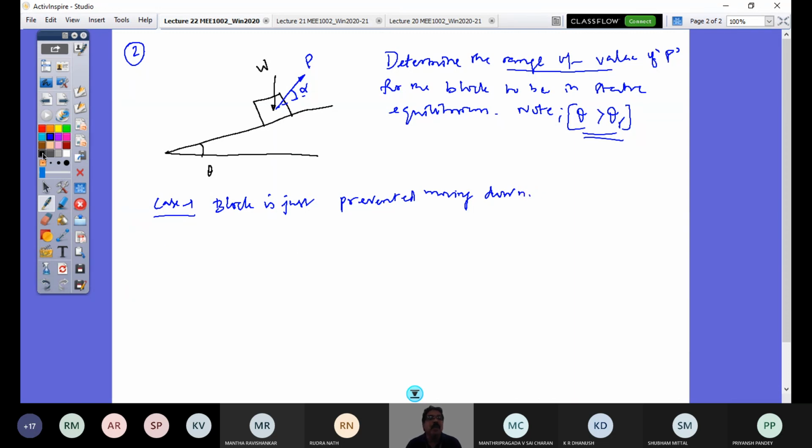So at that point of time, what would be my free body diagram? See, drawing the free body diagram, carefully listen and watch how I do it. I expect the same way you are doing it. If you follow the same manner, drawing the diagram, explaining in the examination, you would get good marks. So this value is now W. And I would now draw the normal. Since there is no dimension involved, I take this as collinear with this, right? I was telling you the reason. So this is N. Now what is the direction of friction force?